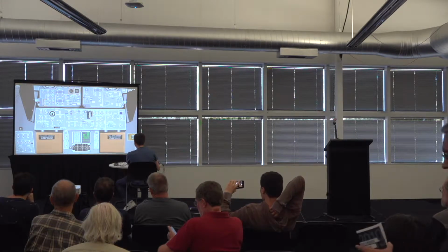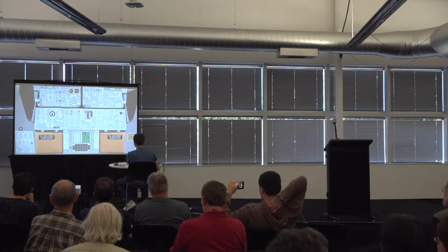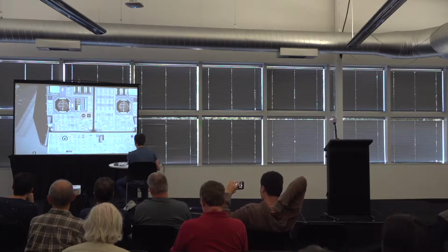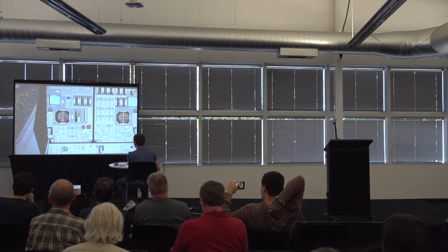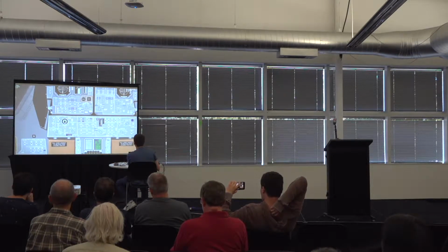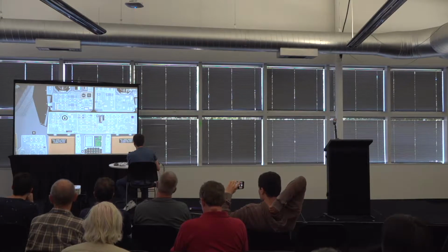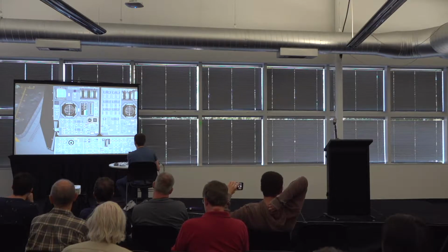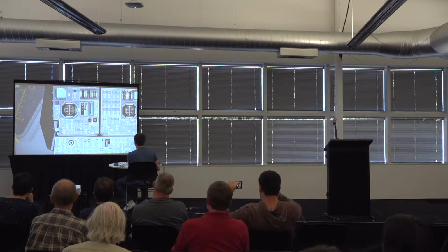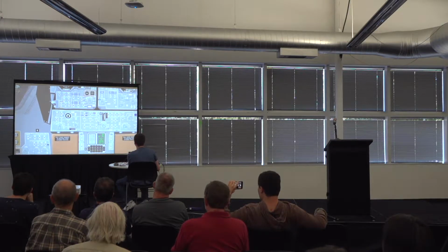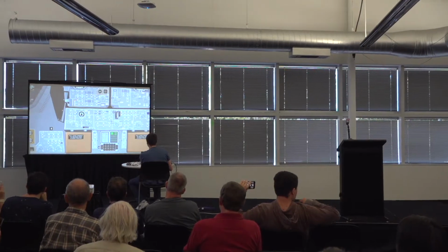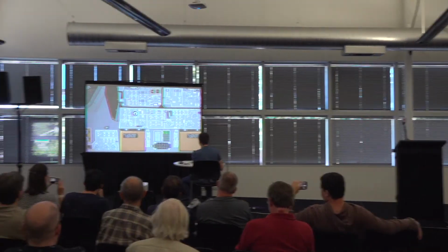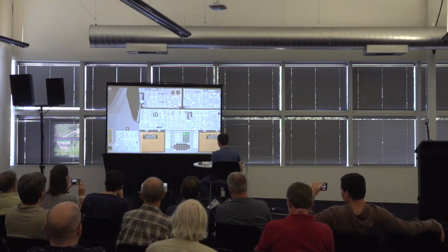I'm going to hit enter to skip the final alignment of the inertial measurement unit. And now I'm going to set some switches to give the AGC control over these displays up here, which I'll talk about in a bit. And now on flashing verb 50, noun 18, I can hit proceed, and the AGC is going to maneuver the lunar module to the burn attitude. So this is the direction that the AGC wants the LEM to be facing when it turns on the engine. Enter to go past the screen, and now it's going to do a lot of calculation to figure out exactly where we're going to be at ignition minus 30 seconds.